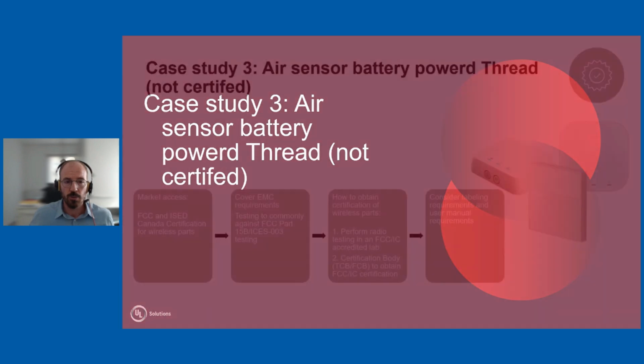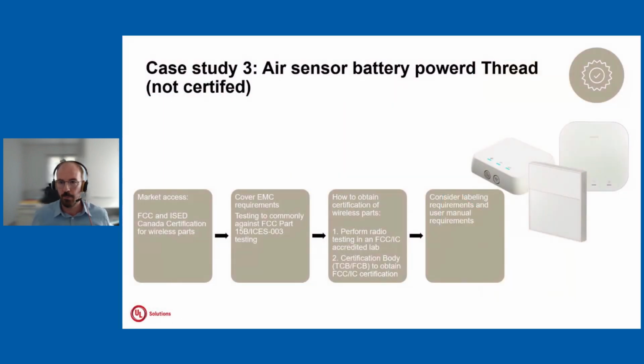And now let's jump to the, I would say, more complex scenario. And this complex scenario is, well, actually, this thread radio part, it's not a radio module. It's a chipset. It's something coming from the chipset vendor, and I have done my own design. I have put the chipset with the oscillator or the quartz. I have then done all the antenna path with the different components, the antenna matching. I have designed the antenna, or I have used an external antenna, both in the market.